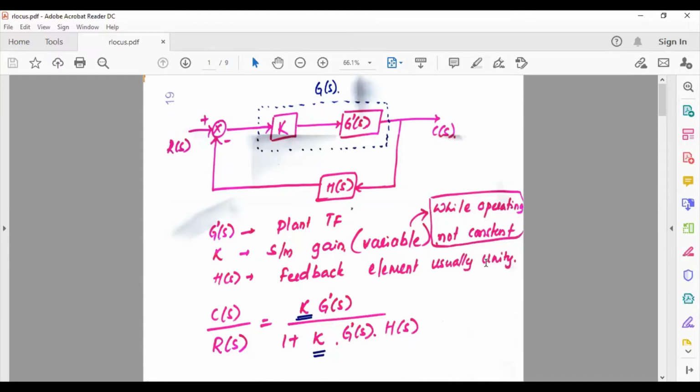So that element is called a delay. I mean, the time taken to transfer that signal from the head to the combustion chamber is called a delay in communication. That delay will usually be put in the feedback path in complicated systems. The delay is written in terms of Laplace transform and substituted here, usually as an exponential term, something like e raised to minus 2 milli s, into s. But we are not going to do that now, and we assume the feedback equal to unity.